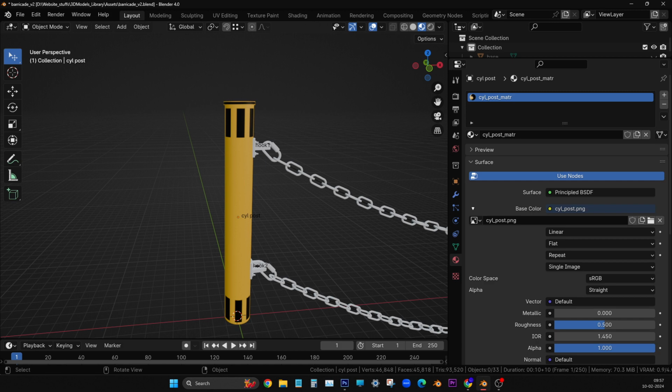Then select the master from whom you are going to take the material, shift select, right? Very good. Press Control L, and then link materials, the third one. Yeah, now it's copied.